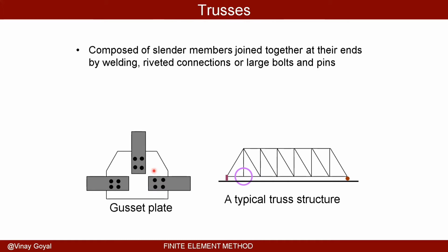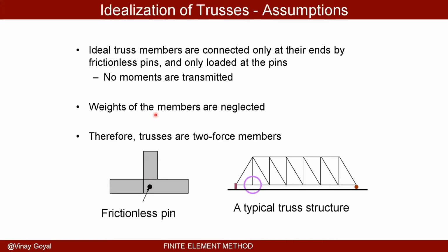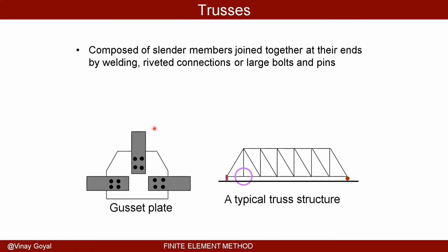So say I predict that this pin loads up this force member 4,000 pounds going up. Okay, well, then 4 bolts have to take the 4,000 pounds. Therefore, each bolt has to take 1,000 pounds because I have 4 bolts. And then you can start making some hand calculations to then increase your knowledge about these joints.